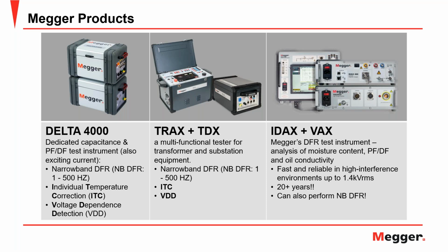And again, it comes with a module. This module here is my high voltage module that will allow me to go up to 12 kV and do my narrowband dielectric frequency response, my ITC, and my VDD. Last but not least, a unit that we are very familiar with and has been in the market for the last 24 years, and it has created for us a huge database of information, and we are now able to look into the correlation between power factor, line frequency, the narrowband, and the full spectrum DFR with the IDAX.